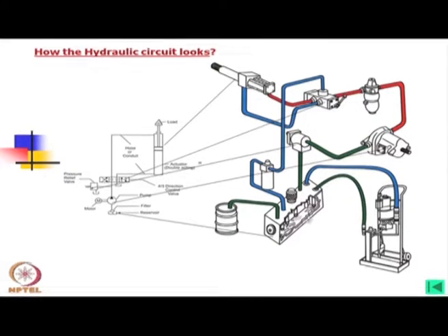This we can do from time to time, it may be after 6 months, it may be after 3 months, depending on the use. We can pump out the oil, filter it and again put it inside to reduce the contamination. Okay. Now, as well, what we find here is sometimes the inline filter, through which the oil is further filtered before entering the actual system.